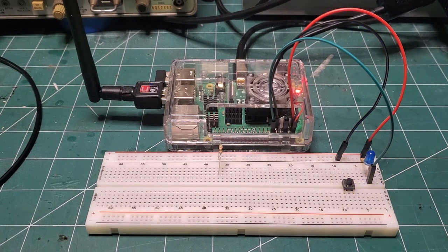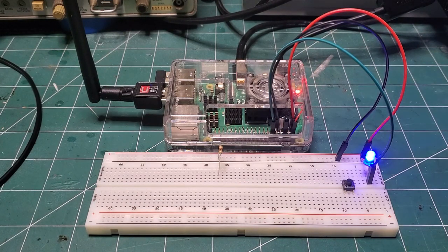So in the video I'm putting together here, some of the things that I'll go through are, firstly, what GPIO capabilities exist on the Pi and how they differ from, let's say, the STM stuff that I've been doing earlier. What C and C++ libraries exist to access the GPIO pins. And then I've got some specific nuts and bolts examples for GPIO input and output, serial or UART access, SPI, I2C, and we'll see where we go.